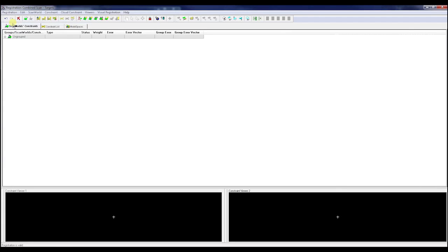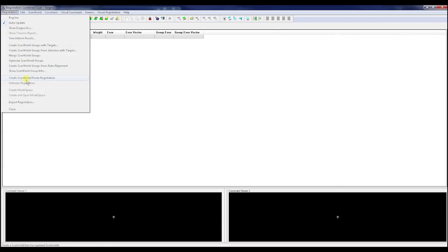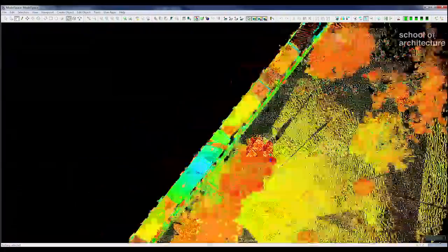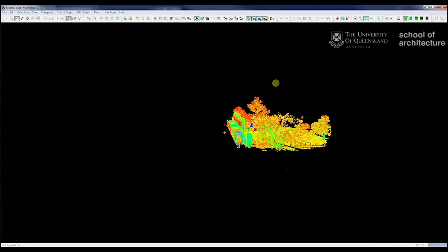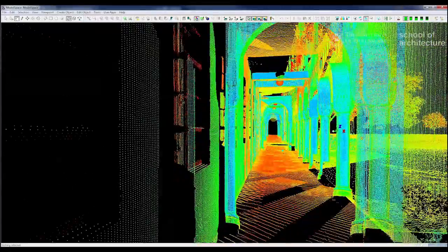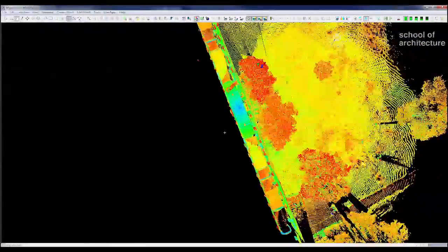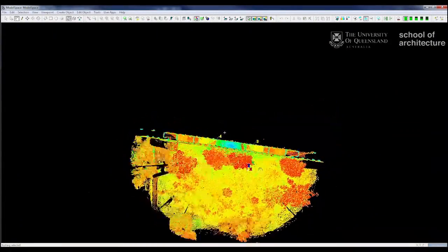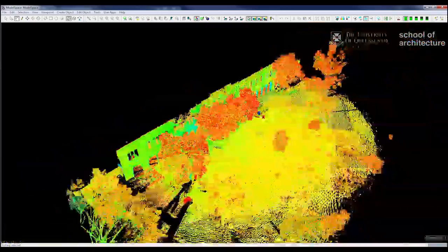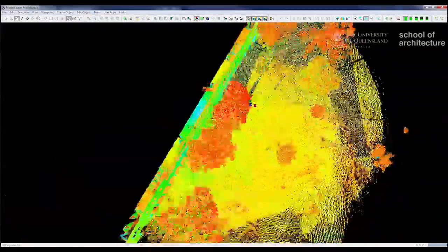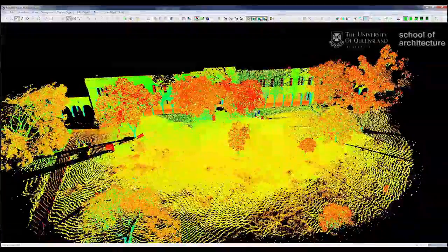From there, just press auto update. And we can create our scan mode and freeze our registration again. Create an open model space. You can see now that I must have missed a little bit of data, but all our data has been removed. So we now have a much cleaner scan. And we can then unify this and get this ready to take into MeshLab and ready to try and create some meshes out of it.